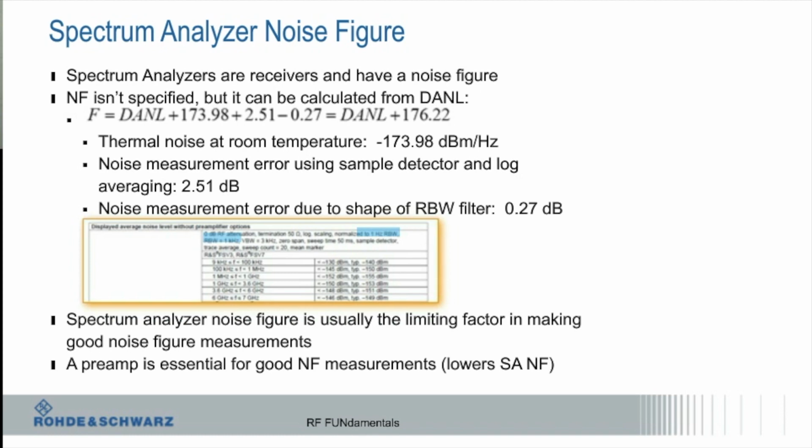Yes, FFT is fine. In fact, you're better off in FFT mode. It's much faster. Depending on the situation, you might find it's orders of magnitude faster. But don't you have to have a wider bandwidth in order to have the FFT work? No, because if you have a wider bandwidth, you have a faster time constant in terms of the analog bandwidth. Then when I do the narrow band filtering, the binning in the FFT, it's done all digitally. So it's much faster. It can do those processes simultaneously in parallel, so it's much, much faster.